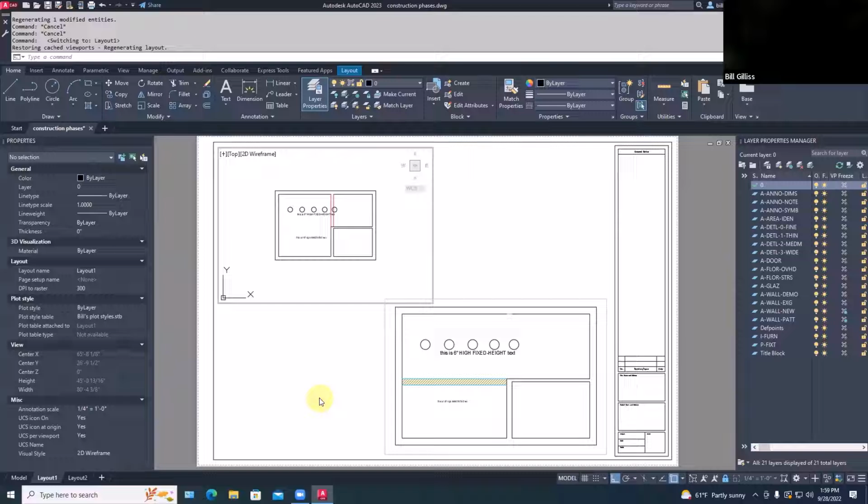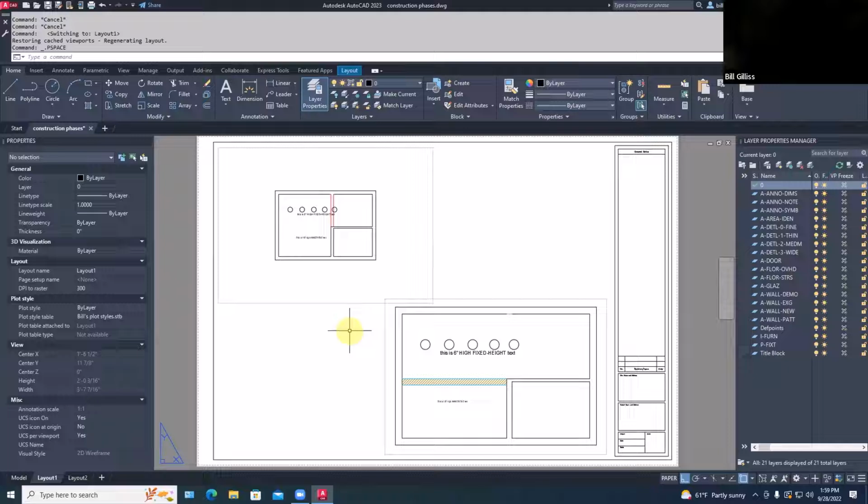The same text style that's read by the dimension styles can also be used for the notes, and that will have that same height, whatever that happens to be. So one text style, one dimension style covers all the bases. So let me show you what that looks like. So this will be a fixed height, let's say a 1/8 of an inch high style. We're going to call it notes, and use that style for everything: for text, for dimensions, for things with leaders on them, the whole gamut. This is the number 3. Yes, fixed height text placed in paperspace. So first we set up the text style and then refer to that in the dimension style.